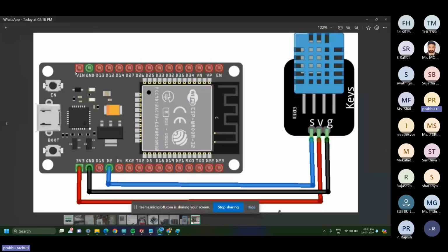To know these kinds of things, you have to go through the data specifications of the ESP32 module, and the GPIO as well, as you saw in yesterday's class. VIN is the input power supply where you can give a 5 volt supply. This will step down the voltage to 3.3 volts using the 3.3 volts regulator, the AMS1117 voltage regulator, which steps down DC to DC from 5 volts to 3.3. It's a fixed voltage, not a variable voltage. It directly steps down to 3.3 and gives that voltage to the entire chip.